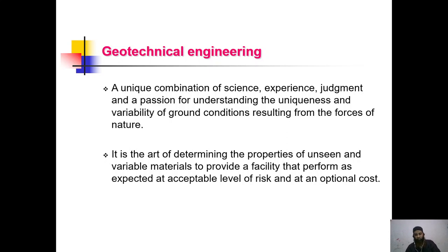Basically, what happens is how the loads are transferred from one element to another element. First the load from the slab is transferred onto the beams, and from the beams to the columns, and from the columns onto the footings, and this load on the footing is now transferred onto the soil. So basically the soil needs to resist the total loads coming from these different elements.